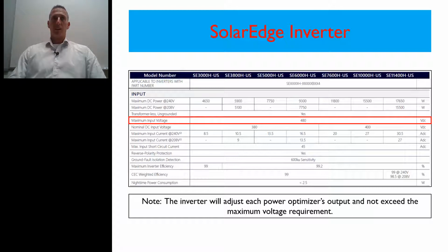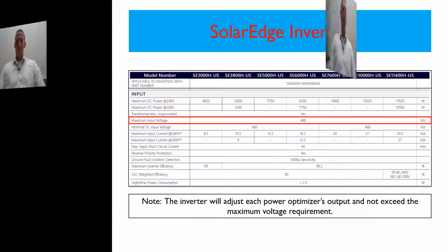Because on the minimum string lengths on those converters, if you connect too few, the system won't be able to turn on, and if you connect too many, you're going to exceed the rating of the inverter. So you want to make sure you balance that.